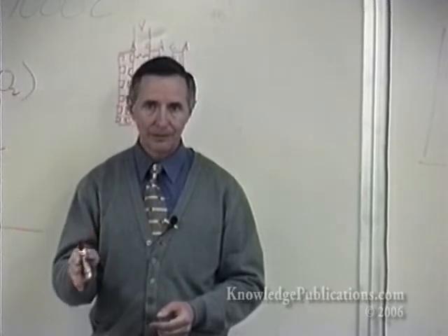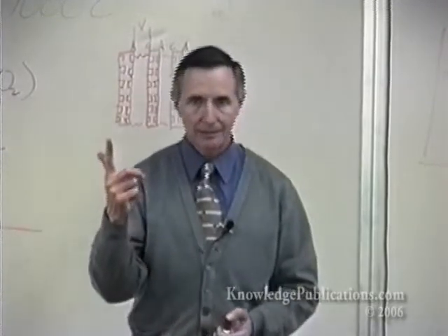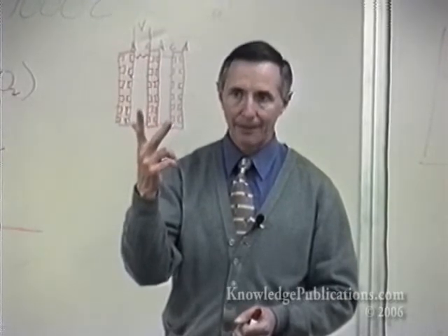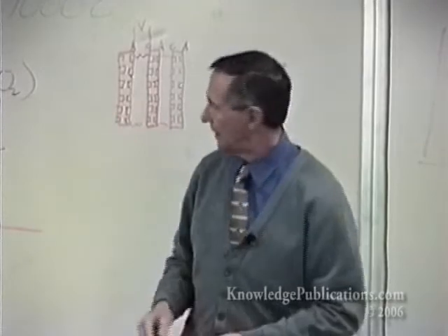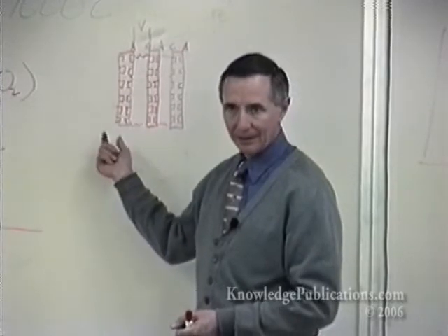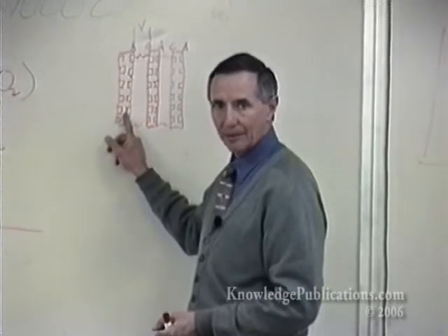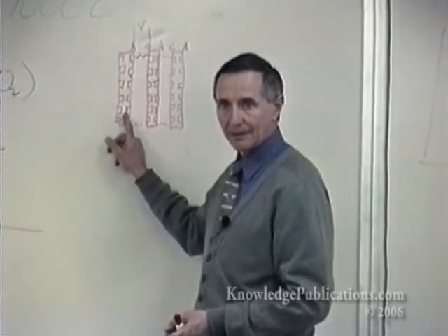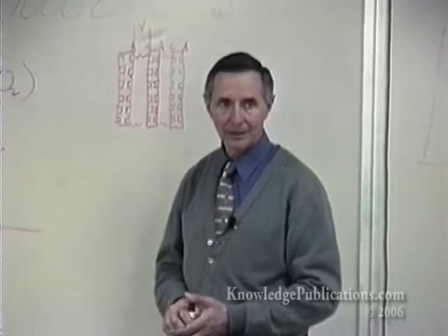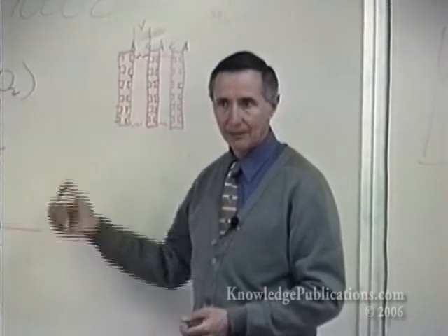In terms of improving the system, you can look by rule of thumb at three major opportunities. One is in the electrodes. The second one is in the cost of the membrane. Right under the electrodes is the membrane cost. The third is in this flow plate, the system that looks like an electrode to you because of the way you've doped it or the way you've stacked it. But these are expensive too. They're typically made of carbon or graphite. And they become more complicated every year because somebody does more by way of making a heat addition to start them up, a heat subtraction to keep them from overheating at high amperage, and they become more complicated to build.